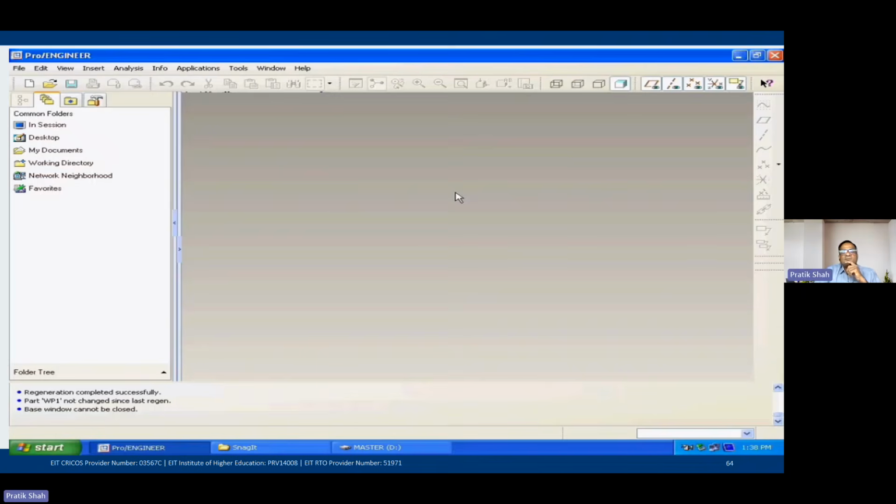I said that I have to start machining from this. You have to be careful that the raw material size which you are using in the modeling, the same raw material size should be fixed in the machine. So there you go. You are now with the single point tool and the tool path. This is it. It is now simulating for you.